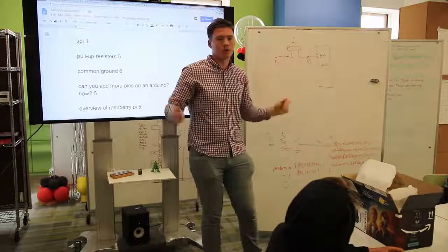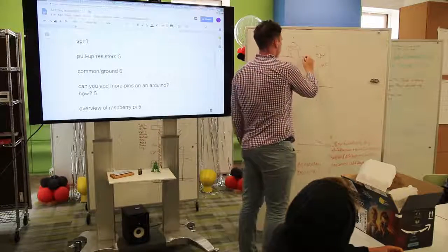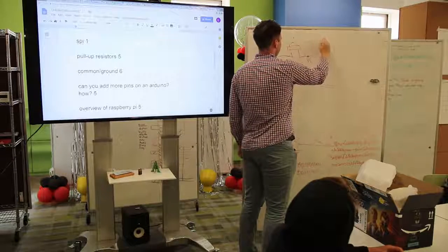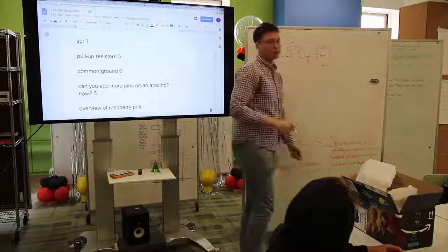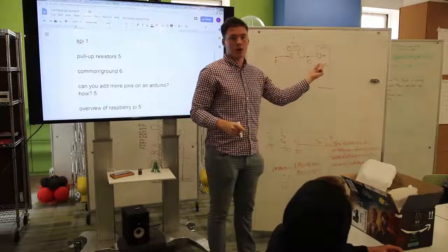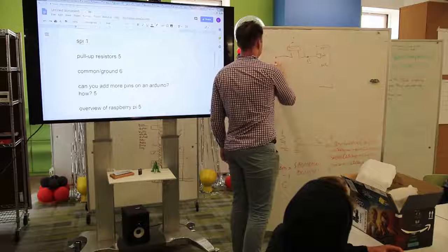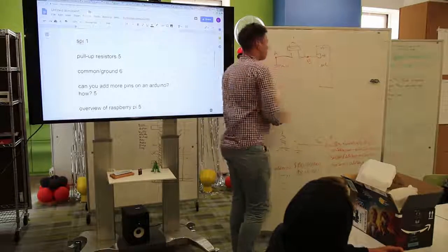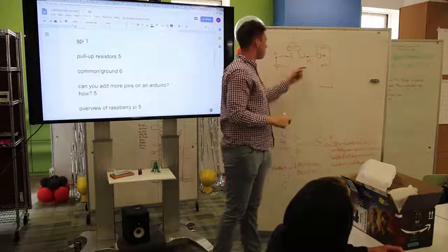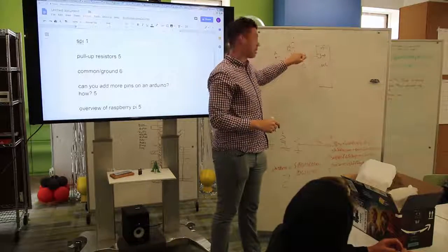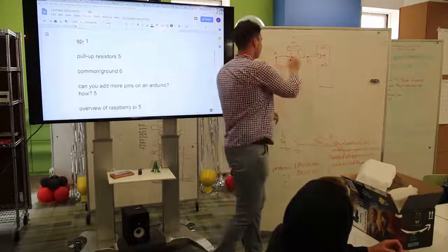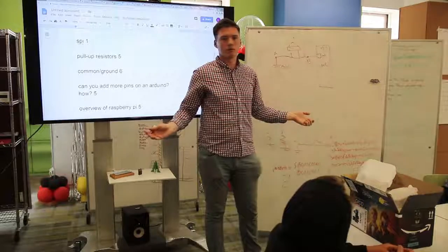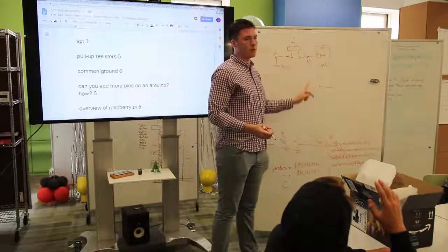Okay, I'll guess. I'll try something. Let's see if this works. I'm going to connect this to plus 5 volts, because that's a 1, that's a high. And the other side, I'll connect this to ground. This is 0 volts, and this is plus 5 volts. So when it's not pressed, it sees 5 volts, because this isn't connected. And when it's pressed, now that 0 volts is connected here. It's perfect, right? Is there any problem with that? Can anyone see a problem that might arise when I press the switch?